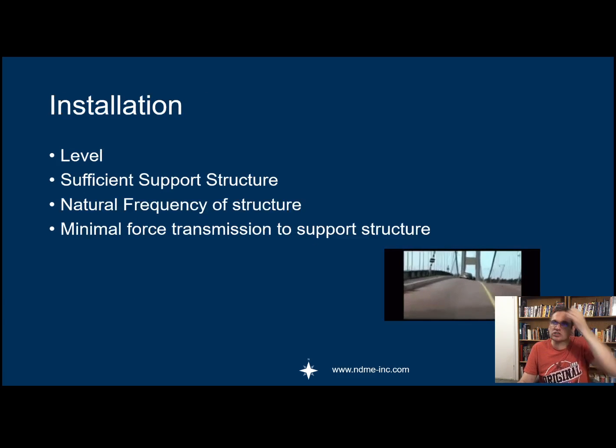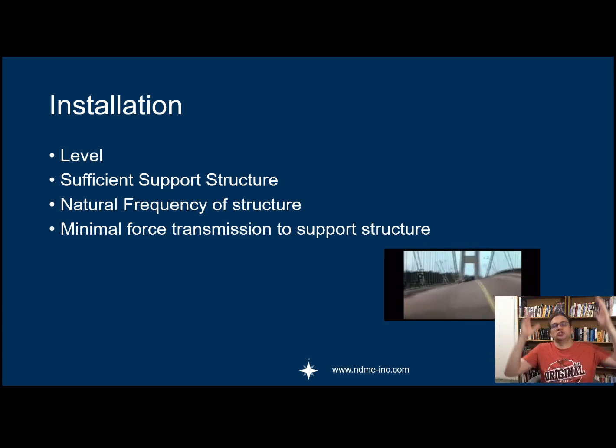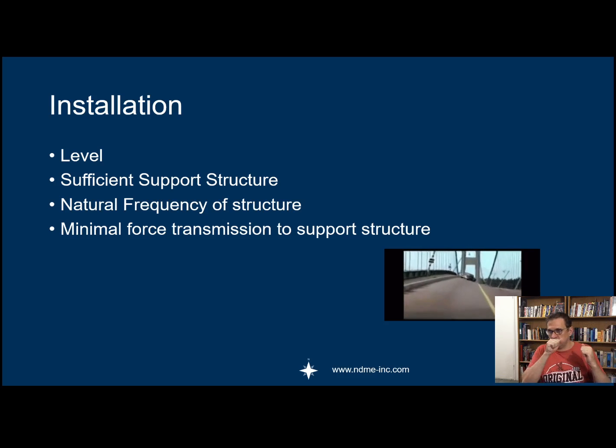Then installation. The other thing that's interesting about a vibrating screen, especially in design and installation, is that the screen vibrates. And if you put it at the top of the building, you can imagine it shakes the building. It could create what you can see in this picture here, especially if you get to the harmonic frequency. So that is a specialized field, and something else that you need to look out for when you design a screen, and that's why often it's a good idea to put screens towards the lower floors of a building to prevent this excessive vibration of the building. It has an impact on the structure that you need and can push the costs up. So as a general rule, try and put the screens lower down in the building if you can.